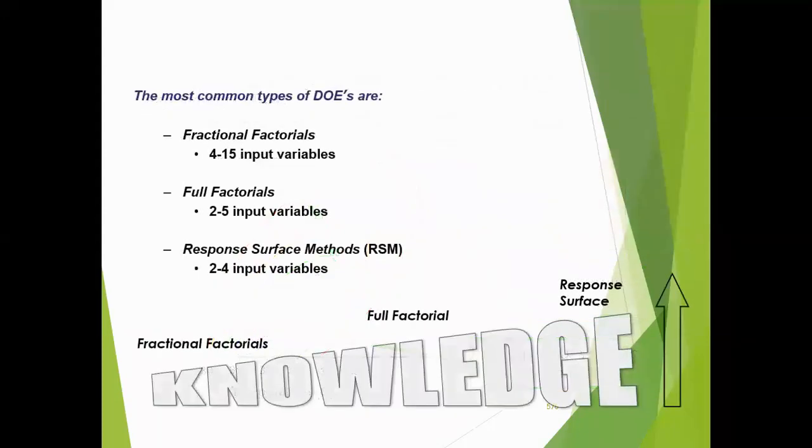Now, at a very high level, there are 2-3 different types of DOEs that are used. There's something called full factorial DOE, which means if you have 2 variables with 5 different levels, you try out all the possible combinations and then you choose the most optimal one. This is good for a small number of variables and a small number of combinations. It may not be the most effective in terms of cost; we will end up spending more money doing the experiments.